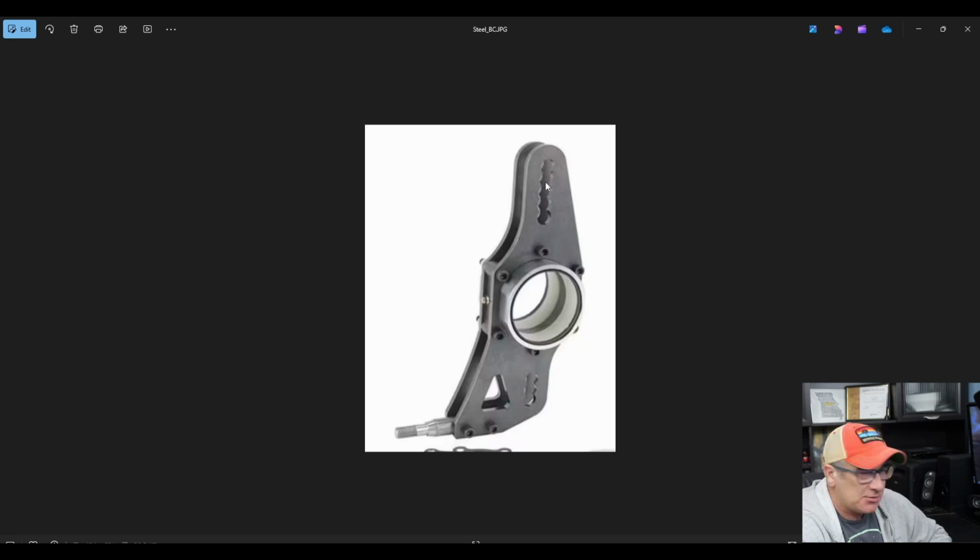You see there are some different adjustment points where you can mount that 4-bar link. And on the lower, just as well, there are some adjustments, but this is where the lower 4-bar link would connect. Then the shock connects to a third point on this bird cage, and that is where you get the 3 connection points to that bird cage.